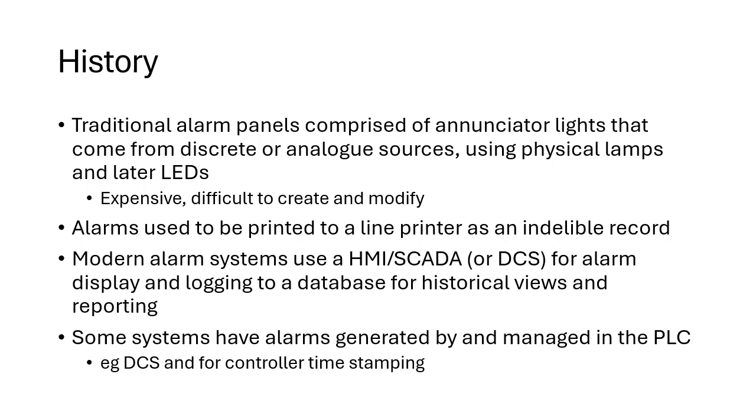As an aside, some systems also have the alarms generated by and managed in the PLC. This is quite common in distributed control systems. And another benefit is it means you can get controller time stamping. So in some large systems, you need very accurate time stamping for the alarm. You need to know exactly when it occurred.